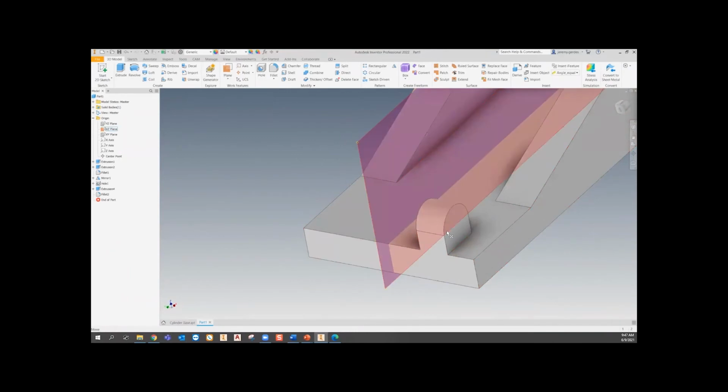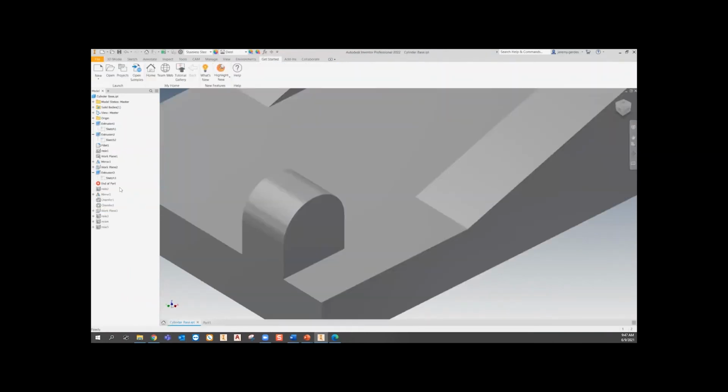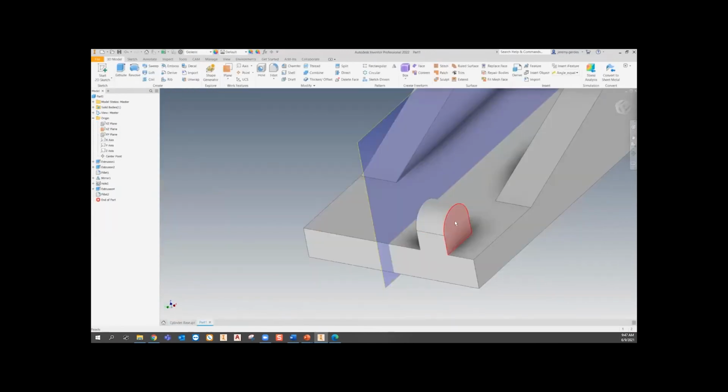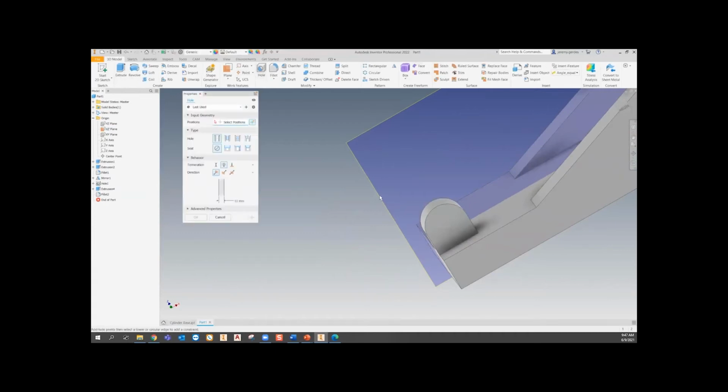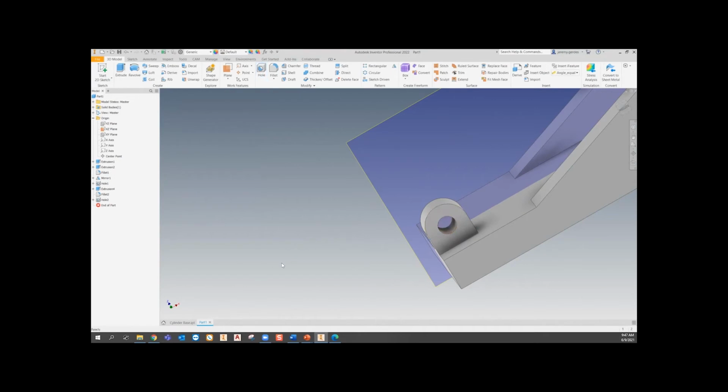Okay, so we'll see what's next. I think it was that hole. So they added another hole here. So we can click the hole command, pick the base, then the location, makes it concentric in that radius, and the diameter of that is 8.